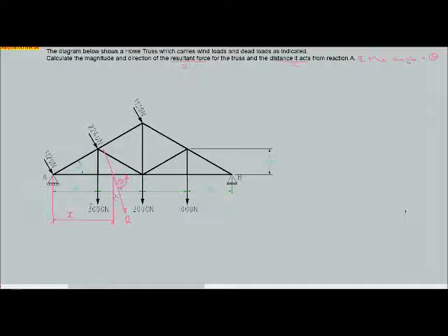Now, each of these forces are vertically down, but these three forces are at an incline. They're at 90 degrees to the rafter, this top member, but they must have different components to them. They have a vertical and a horizontal component. So what we can say is that if we take just one corner, that is acting at 30 degrees to the top rafter, a tie member. Our force, F, this one,